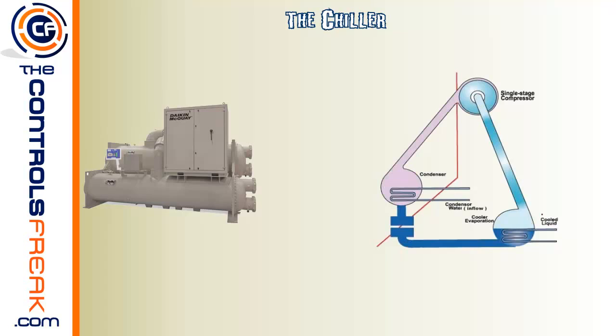One other thing to note about chillers is that in these barrels that you see here, there's many different bolts that come across here that seal up the two ends of this barrel. Inside the main portion of this barrel, these water lines that you see here are actually long tubes that run the full length of the barrels. And so if you ever hear somebody saying they were changing out tubes or they have dead tubes in the barrels, these are the tubes, and there's many of them. I've seen some chiller barrels that had literally 100 or more inside the chiller barrel. So there's tiny little tubes all throughout this chiller barrel. And that's where you get the water running back and forth through this barrel to do the heat transfer.